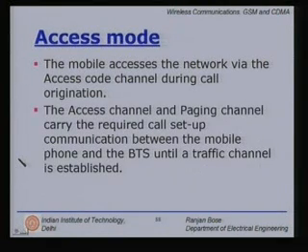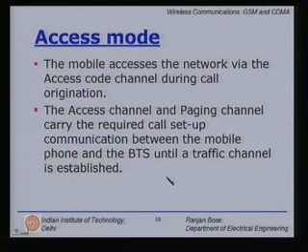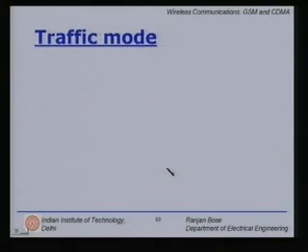The access channel and the paging channels carry the required call setup communication between the mobile phone and the BTS until a traffic channel is established. So, you exchange information on what kind of code will be used. Right? The power is already set up, and once these basic requirements are put together, we try to move to the next mode, which will actually be the traffic mode.